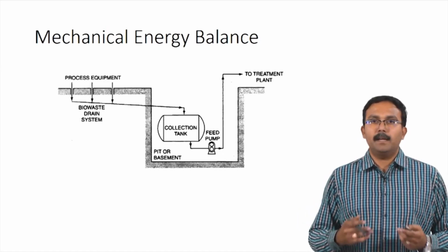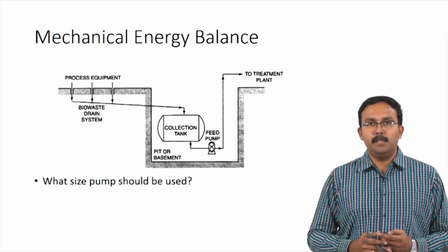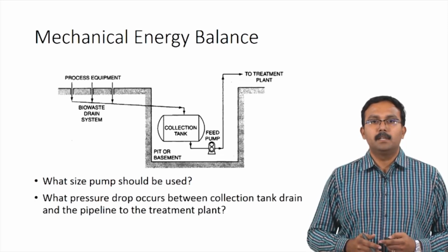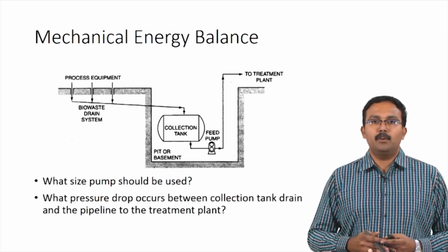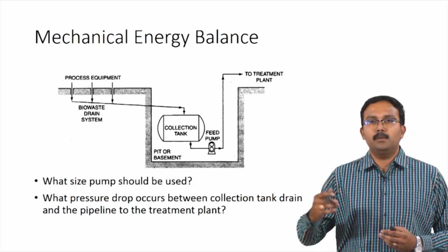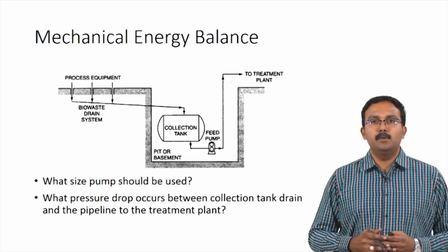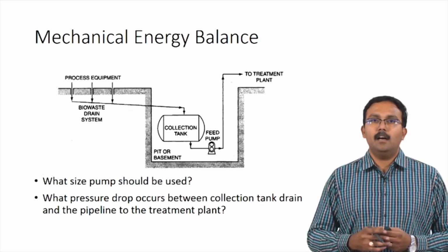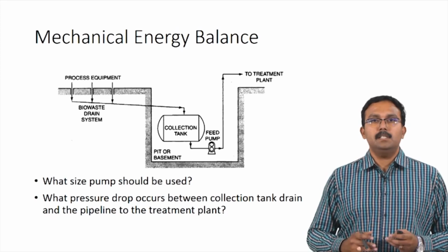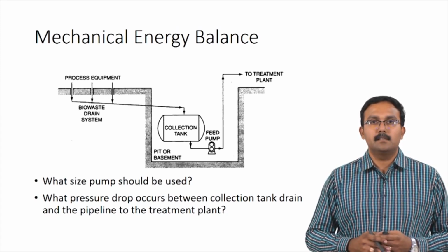You need to perform mechanical energy balances to calculate what size pump should be used, what should be the capacity of the pump, and what would be the pressure drop which occurs between the collection tank drain and the pipeline to the treatment plant. So, to know these values is crucial for designing appropriate equipment. For this reason, we need to fully understand how to perform mechanical energy balances.